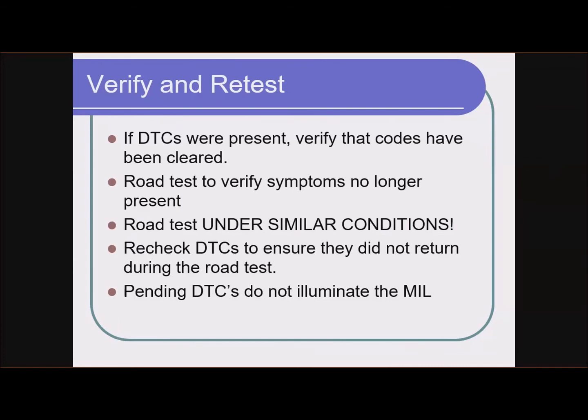But for other things like misfires or lack of performance or stalling or idle quality problems, if you were able to verify that the condition existed before you did your diagnosis and repair, you should be able to verify that the condition does not exist after you've done your repair.